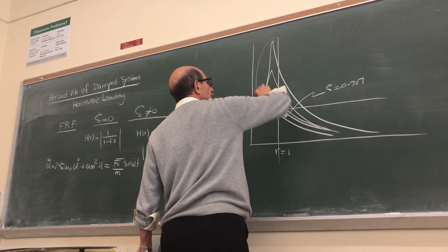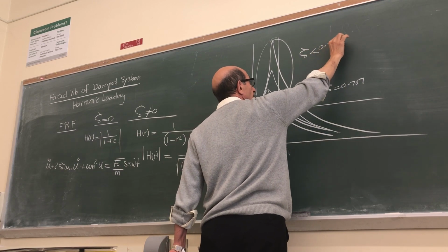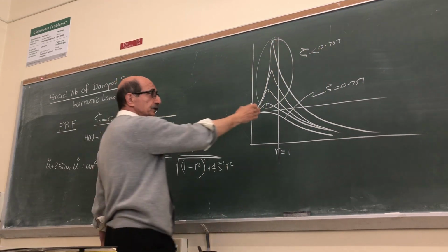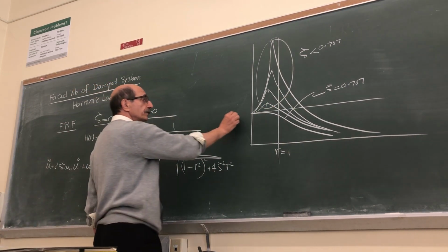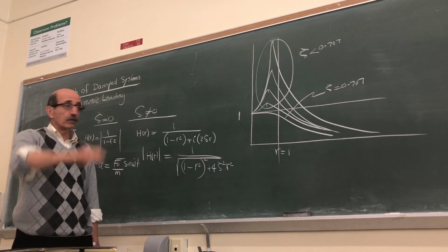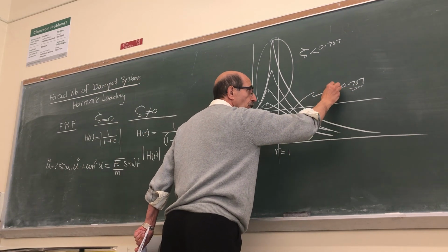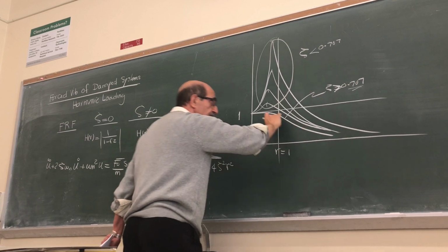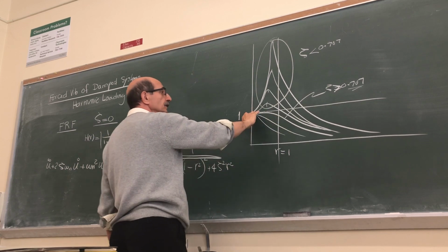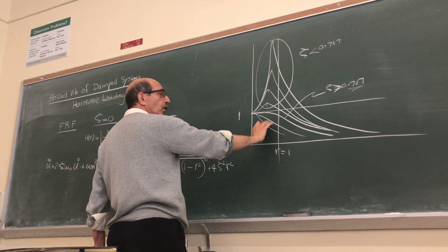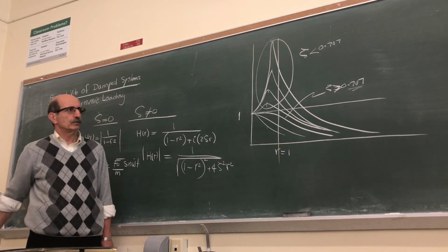So these are all for the case of damping less than 0.707, shifts to the left, and beyond that all the curves are below the static displacement level, for damping ratio of 0.707 or larger. The maximum dynamic response is always less than the corresponding static response. I think we derived that, right? Their equation and so on.